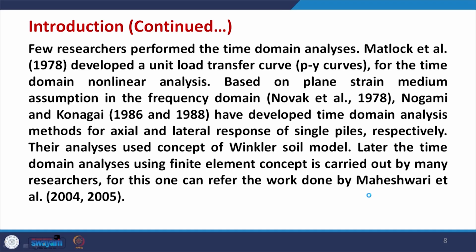Based on the plane strain medium assumption in the frequency domain by Novak et al. of 78, Nogami and Konagai in 1986 and 1988 developed time domain analysis methods for axial and lateral response of single piles respectively. So there are two publications, one for axial response and another for lateral response, of 1988, and these are for single piles.